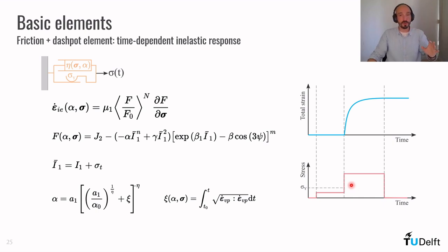So if we think of this as a yield surface, forget about threshold now, and let's move to a more general idea of yield surface. So the yield surface will be the threshold now. The threshold is not just a number, but a surface. And I'm going to show in a few seconds what that is. So that yield surface expands when this alpha decreases. Okay.